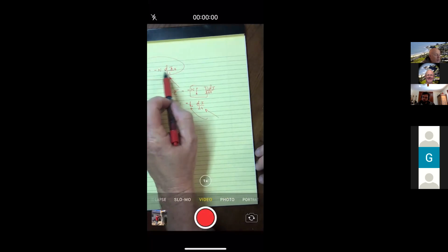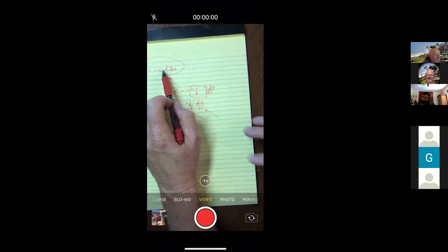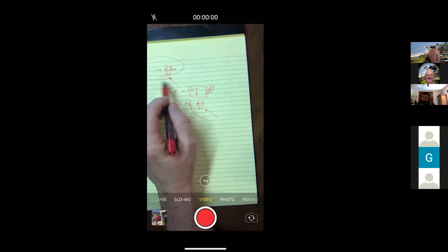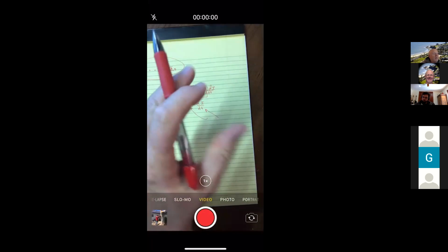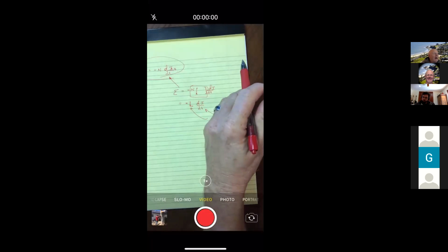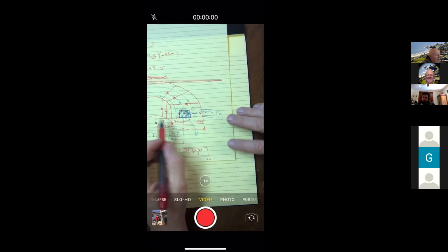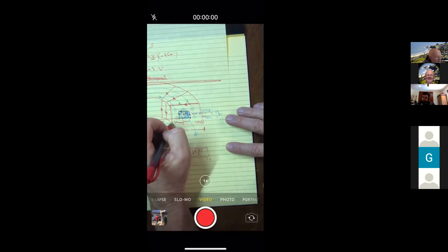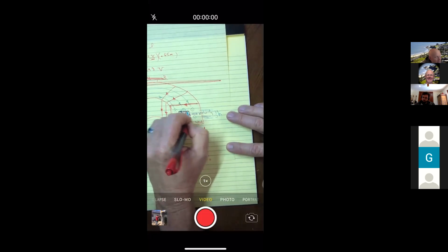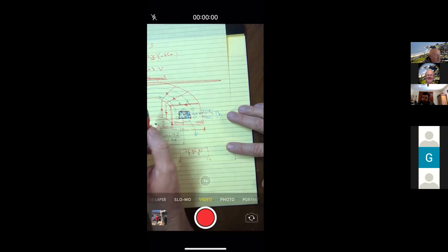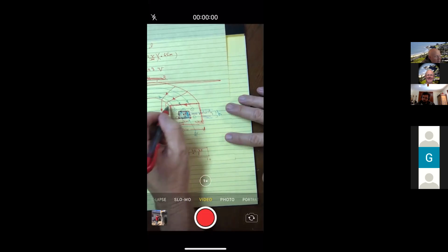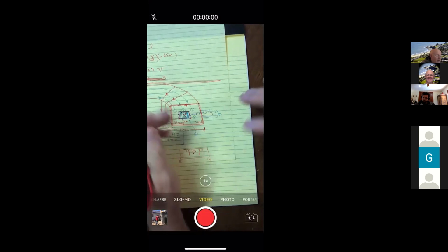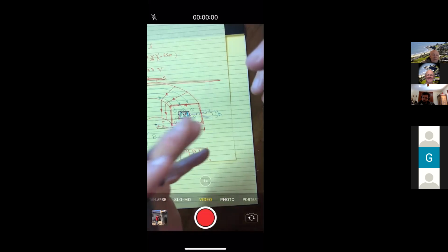And so if you go through the math on this, you'll see in number one, there is no secondary moving object, but you're looking at the flux, and maybe this was your question, it would be the flux over the whole cross-sectional rectangle. Whereas in this problem, I did the flux only within the secondary object, because I want to know the flux in that second object. Whereas if I were to actually solve problem number one, I would take the flux in the whole toroid because it's changing on itself.